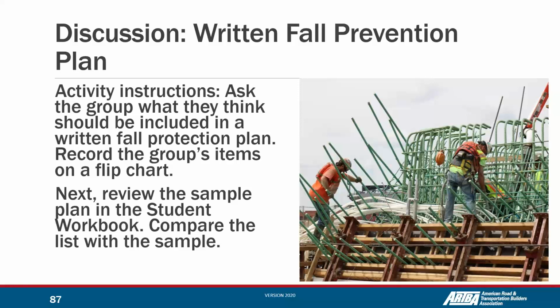So we have to consider the 6 feet rule in regular conditions. We have to consider if we are working on scaffolds, or if we are working with steel erection. Scaffolds is the 10 feet rule, steel erection is the 15 feet rule. And we need to consider if they are going to work vertically or horizontally. So there are many things.